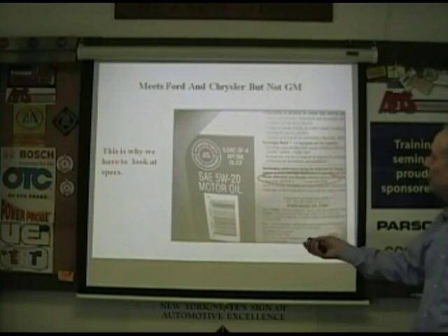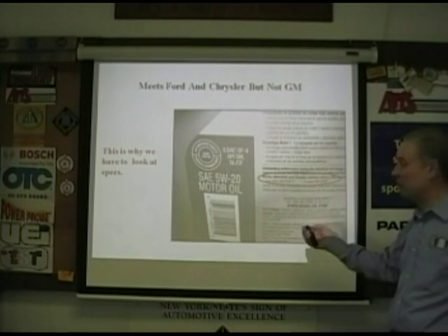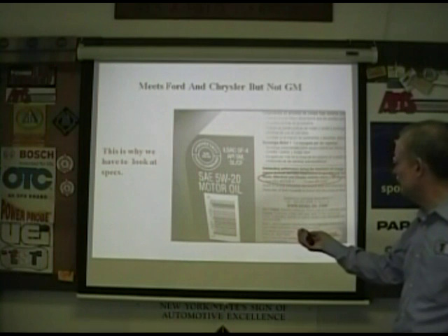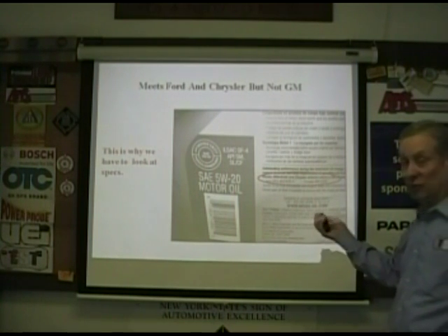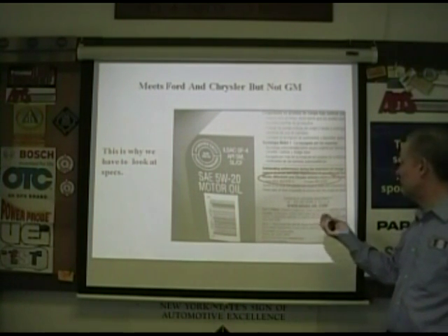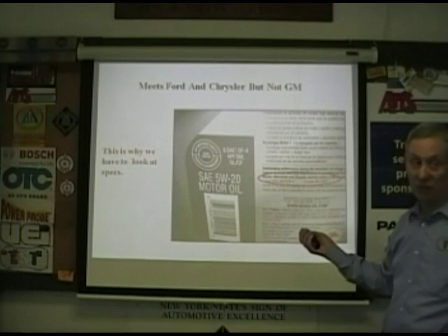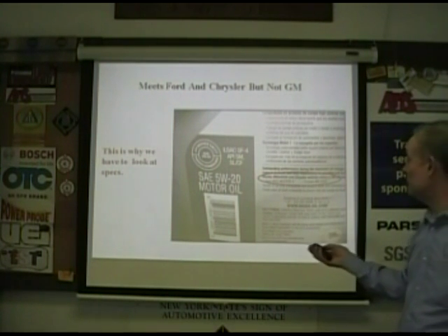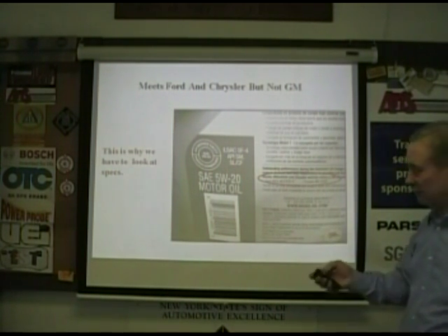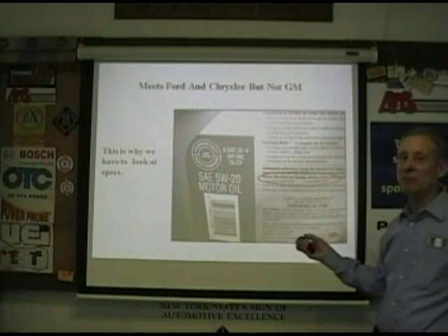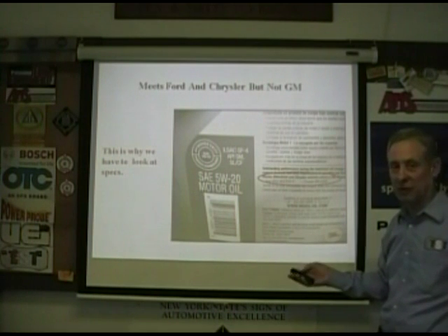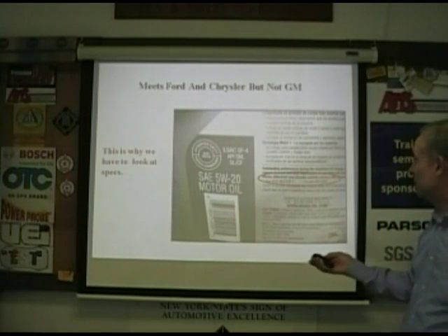Alright, this oil here is a 5W-20, but it only meets two manufacturer specs. This Ford spec, and by the way, manufacturers have different specs. And this says Ford WSS-M2C930-A. It has to be that spec for whatever Ford you have. Same with Chrysler, Chrysler MS-6395. There are multiple specs manufacturers have. As a rule, and we all know rules are made to be broken, the newer spec is backwards compatible, it covers the older spec, but that's not always 100% true.